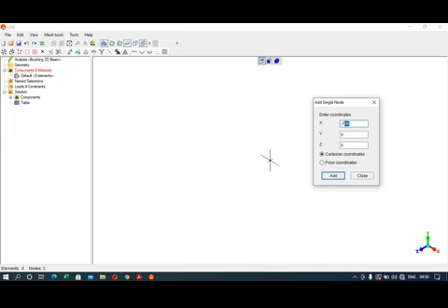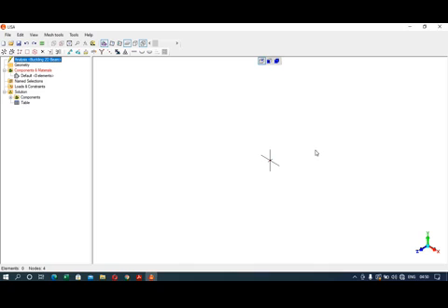And the third element is having length 300, so total minus 1000. Add. You can click on this screen and zoom out with the help of the middle mouse button. Now you can clearly see all the four nodes, node number 1, 2, 3, 4.